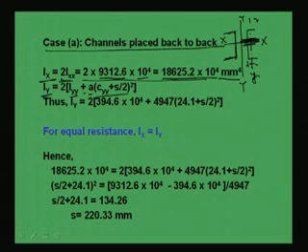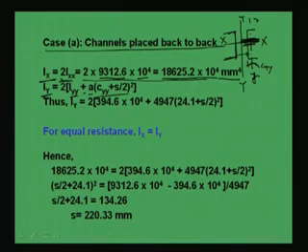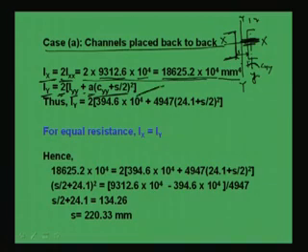R means this is Cyy, the distance from the face to the CG of the section, plus S by 2. So, A into r square means A into Cyy plus S by 2 whole square, and into 2 we have made because of two sections, right. So, Iyy can be found from this expression.